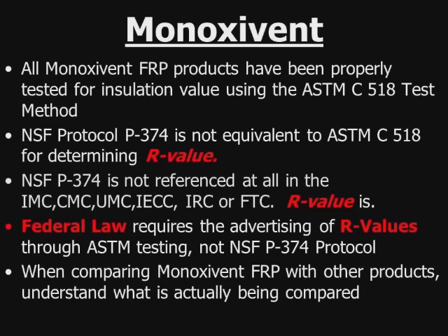And more importantly, throw out all of the codes. Federal law prohibits the advertising of R value through anything other than ASTM. The advertising of R values through NSF protocol is not allowed. It must be through ASTM testing.